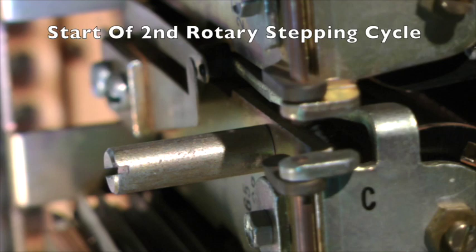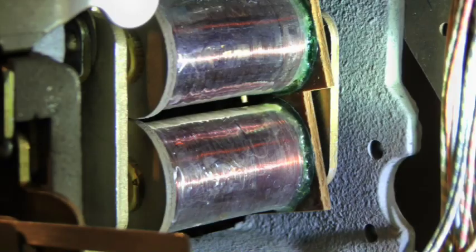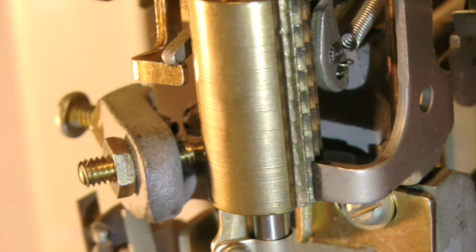With the release of the rotary armature, the path for operating the C relay is closed, and so the C relay reoperates. This energizes the rotary magnets, and so the rotary armature operates. The rotary pawl engages the rotary ratchet, and the shaft is rotated clockwise by 1 step.